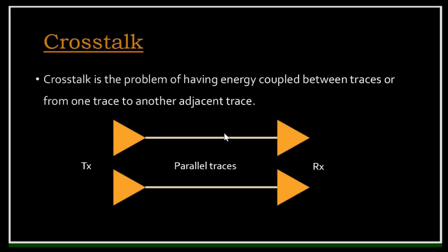So what is crosstalk? Crosstalk is a coupling of energy between the conductors. Or we can say that this crosstalk is usually caused by mutual capacitance or mutual inductance. And the level of crosstalk is very high when we choose faster rise time signals or high frequency signals. Voltage or current of one trace interacting with, or passing over to, an adjacent trace, creating unwanted noise, is crosstalk.